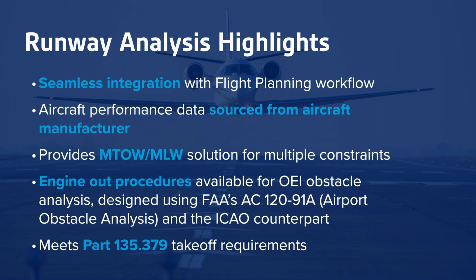I mentioned the engine out procedures that we've got available, and Michael's going to go into a bit more detail around some of the capabilities that we have there. And also the last one is it's meeting Part 135 takeoff requirements. We've integrated things like safety distance factors, and I'm using 1.67, for example, as just a standard operating procedure to make sure I've got enough room. But those are some of the highlights of the capability.